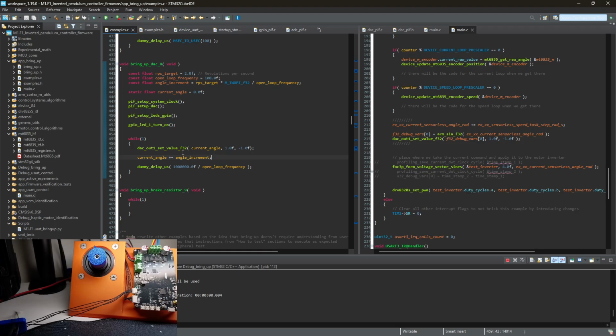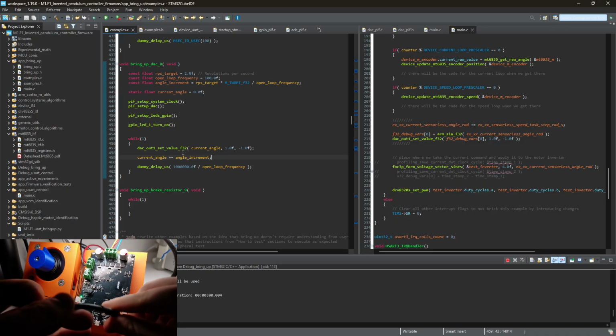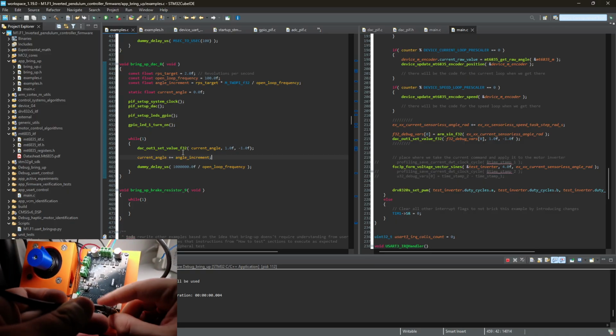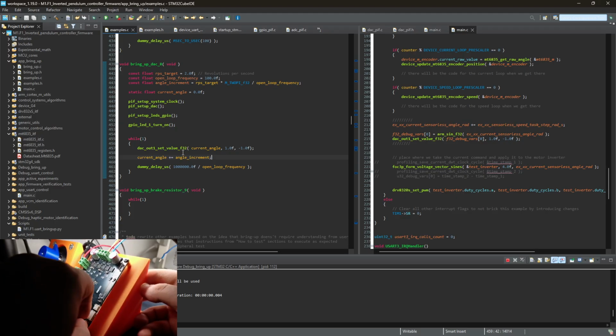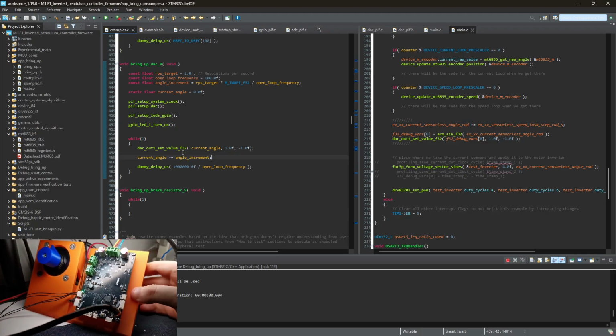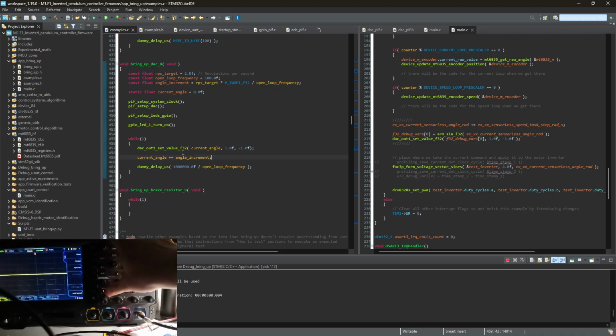So now we need to attach our oscilloscope to a specialized connector we have on the PCB. Just here, and I see nothing because of the camera. I'm sorry. Okay, hello. Now much better. Nice. So we are attached, and let's set it up. So channel 1 is not what we need, we need channel 4. Okay, move it down.